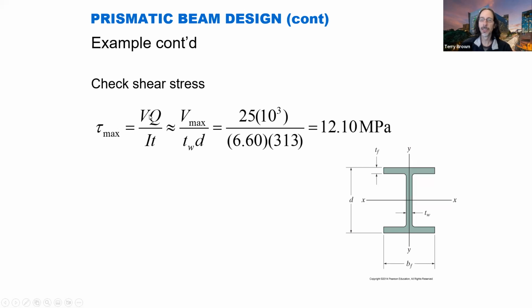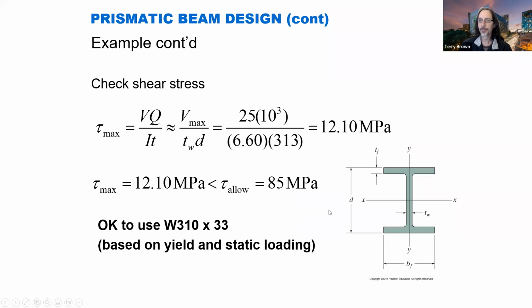As an exercise, it might be worthwhile just to revise using the VQ upon IT and see how close this is. If you want me to, at the end of this video, I might come back and do that calculation if anyone wants me to revise this shear stress formula. All right, so this is well below the allowable shear stress that we had of 85 megapascals, so that's all good.